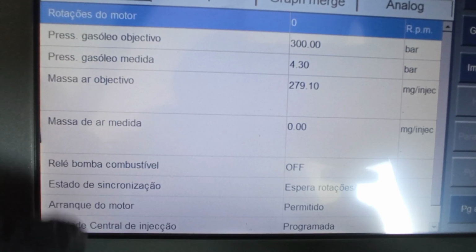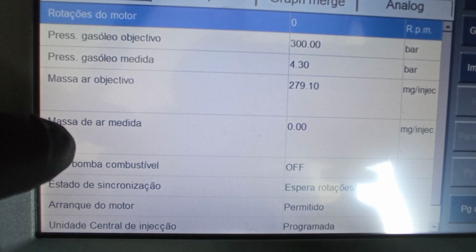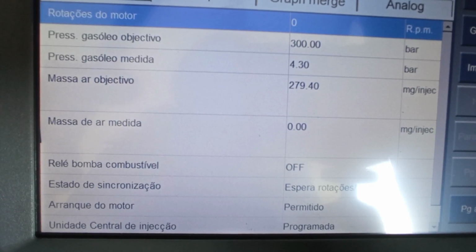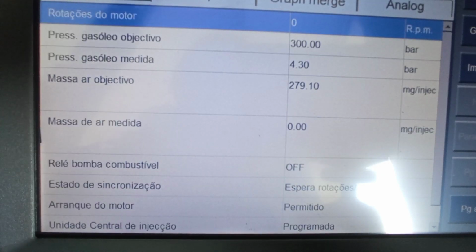Also, for each and every one of these parameters, we can have a problem on the ECU, okay? So I will not repeat that time after time. So ECU on all of this, wiring loom on all of this, and then you can have sensors, actuators, leaks.